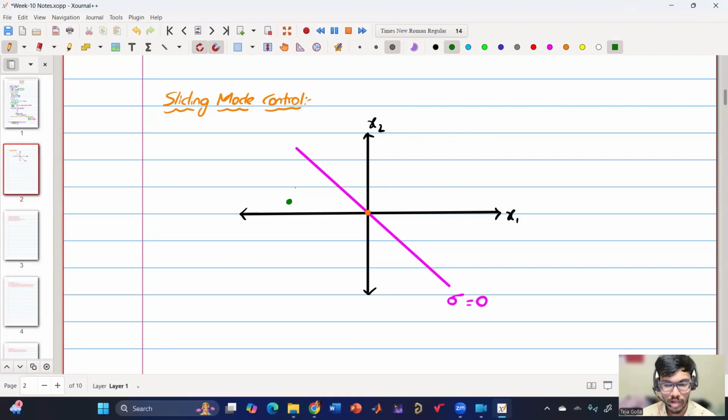In the case of time optimal control, that basically means single switching: one on time plus one off time. So we have to find this sigma equals 0 surface so that my converter will go in this way. During on, say it is going like this, and during off, it should reach this point.